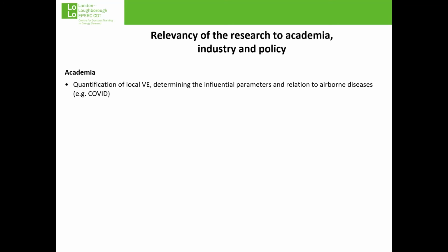However, the perfect mixing performance of NV systems demonstrated as a result of this research could be something not desirable, as it may promote the transmission of the disease. Instead of a perfectly mixed indoor air condition, an NV system providing a directional flow could be more beneficial in critical locations to prevent the spread of airborne diseases.